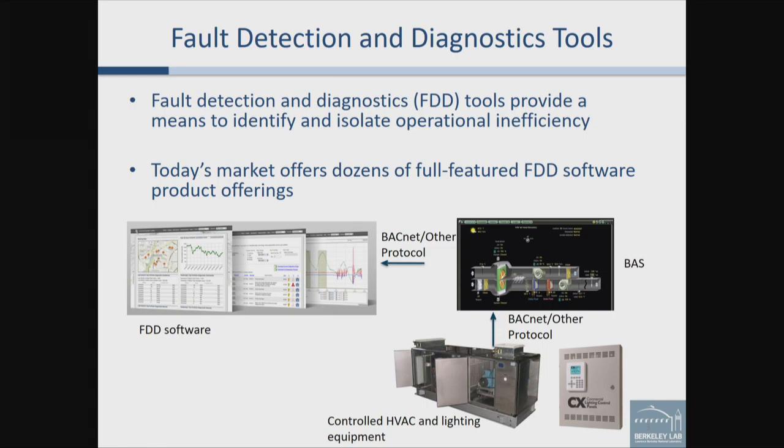The FDD tool is built on top of the building control system. It is third-party software. It reads the data from the building automation system: the temperature, the pressure, the control signal, the schedule. It reads all these real-time time series operational data from the building automation system.